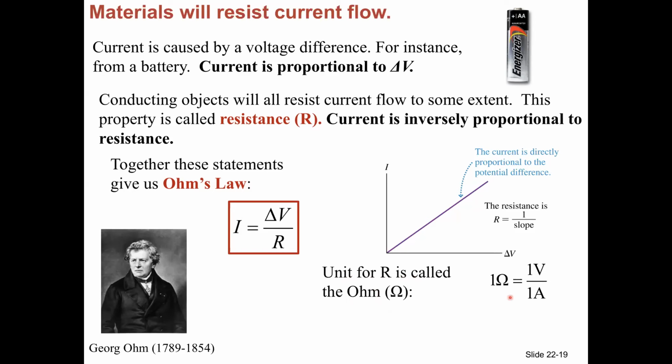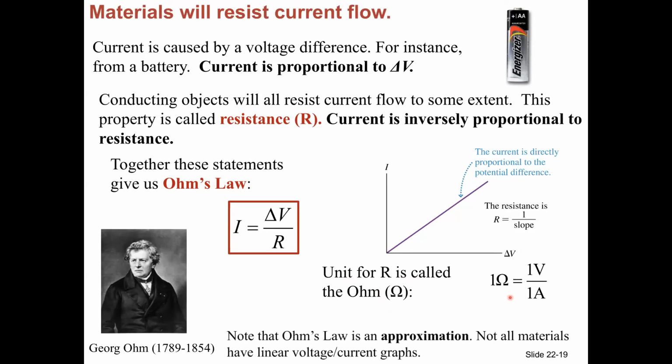Of course, fundamentally, Ohm's law is really an approximation. At some point, if you apply enough voltage to a material and you start pushing enough current through that material, it's going to heat up, eventually melt or burn. Or in some cases, the material might not melt or burn or fall apart, but it might start breaking this linear trend. And it might become exponential or start leveling off. So this is really an approximation, but it's a fairly good one.